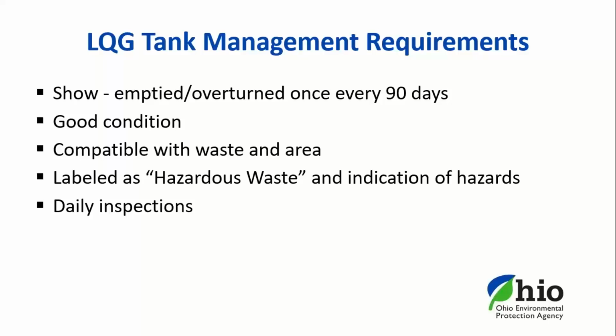So since the rules for LQGs storing hazardous waste in tanks are lengthy, we've just listed a brief summary here on the slides. You'll want to refer to the full rule for all of the requirements. LQGs can accumulate hazardous waste in tanks for up to 90 days without a permit. The tanks need to be labeled as hazardous waste and also with an indication of the hazards. And the tanks need to be inspected daily to identify any leaks, deterioration, corrosion, or structural fatigue in any portion of the tank system components.